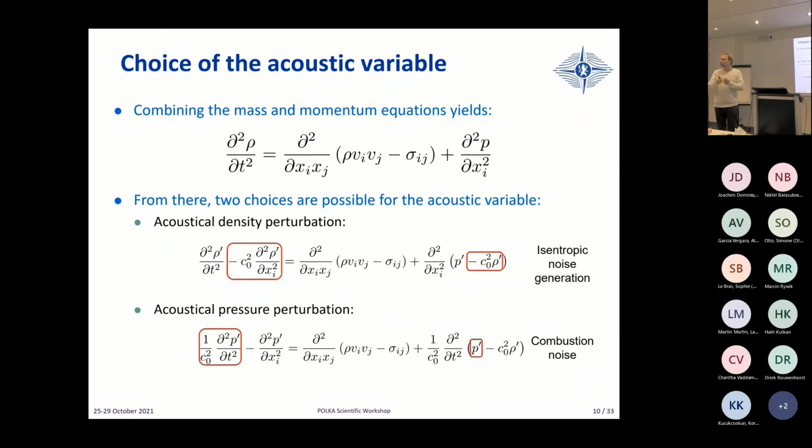But numerical errors will typically not behave the same way, because numerical errors will behave as quadrupoles, while in here numerical errors will behave as monopoles, and the solution should be monopolar. So it's this form, although a completely arbitrary choice over this one, will usually give you some better results simply due to numerical robustness aspects.